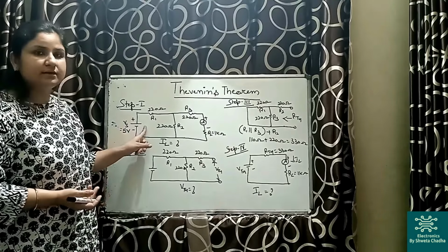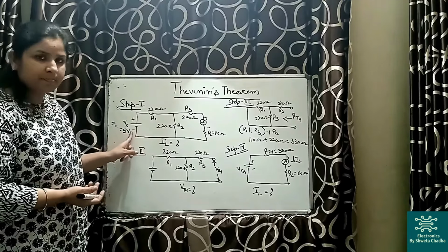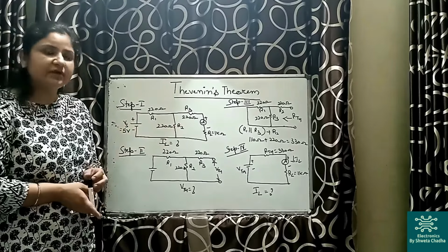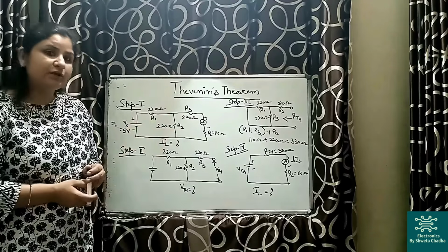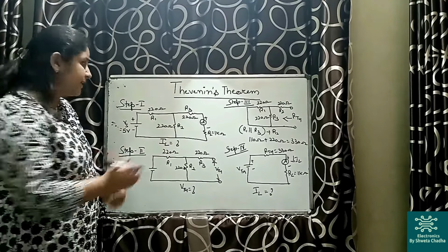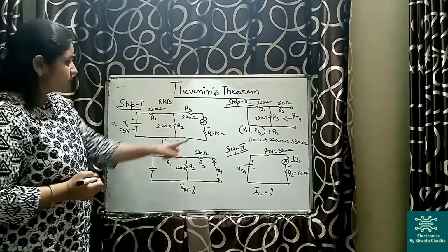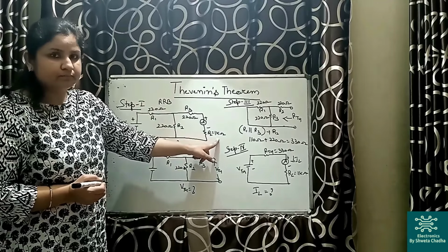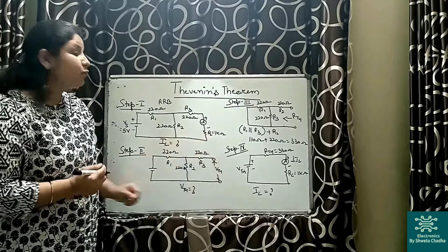First of all, let us consider this circuit diagram. Input voltage Vs is set to 5 volt, with R1, R2, R3. We have taken 3 resistances which are connected in this arrangement. The value will be 220 ohm, that is red, red and brown. Load resistance is 1 kilo ohm: brown, black and red.